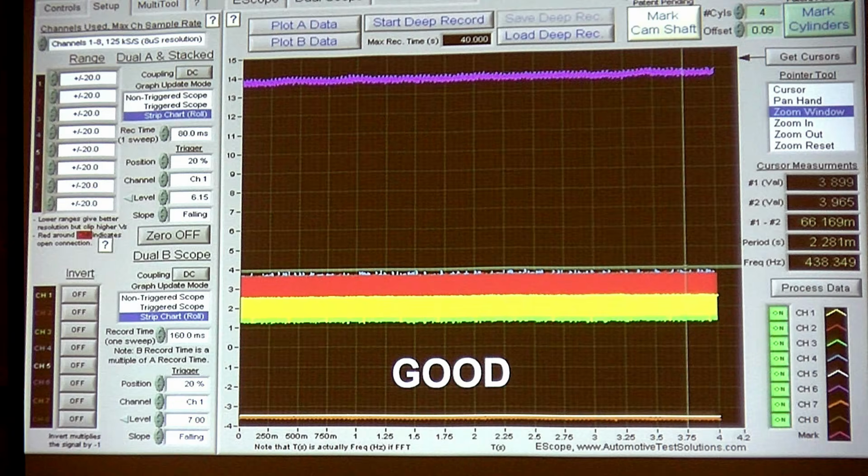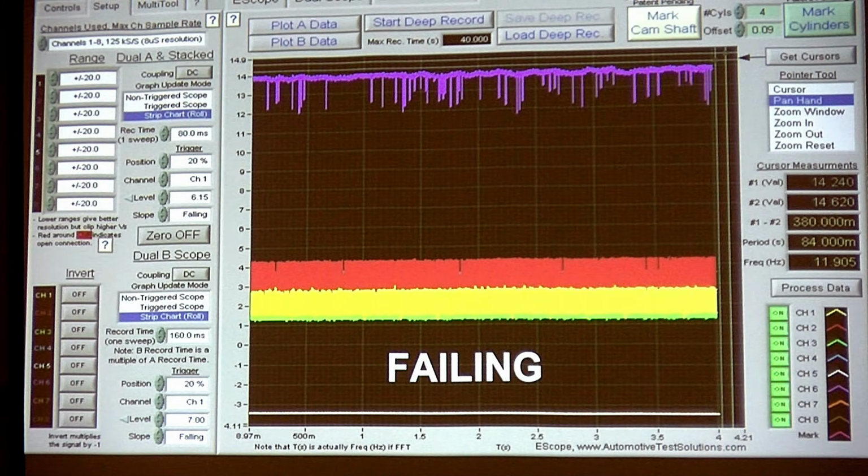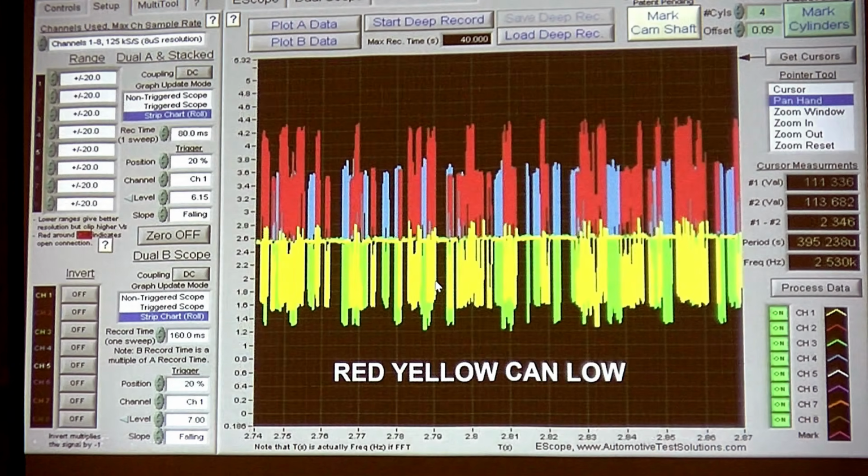And remember, you have to have multiple frames failing because you've got to get to a count high enough to get kicked off the bus. And they do everything they can to not get you kicked off the bus, to make you passive, to make you not be able to talk for a period of time. They're trying to keep it on to where it can recover. Does that make sense? But we all know that now. Okay, so now here it is. We're good. Here we're failing. Notice one of the first things I see start to fail. The power's failing. But also, look down here. Do you see how my CAN signals are failing? That power I'm on is sent out and controlled by the SIM.